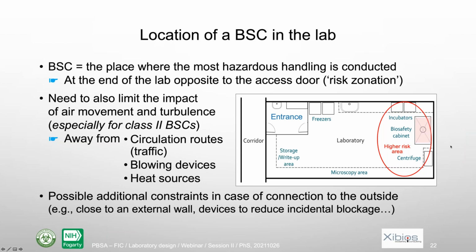So in this case, on the drawing there, you see it's a perfect location. It's at the end of the lab, and people will not work there. If it was in the middle of the lab, that means that some people would go past by, and especially with a class 2 biosafety cabinet, that is likely to disturb the airflow and thus to disturb the level of protection.